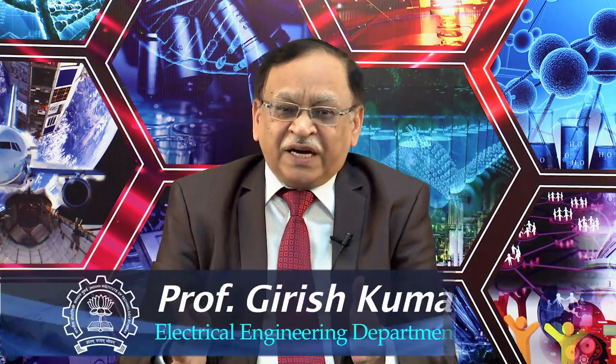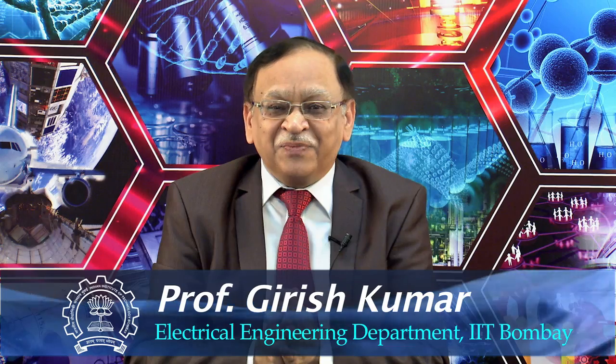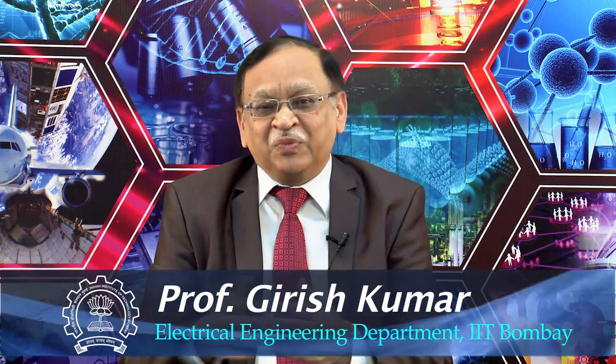So, at higher frequency, really speaking, we have to optimize the gain properly so that we can get a higher gain. And to obtain the higher gain, we have to find gamma in, we have to find gamma out, and then we have to design impedance matching networks at both input and output sides, so that maximum transfer of power takes place from input to the output side.